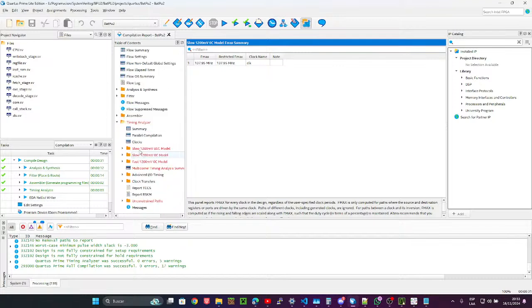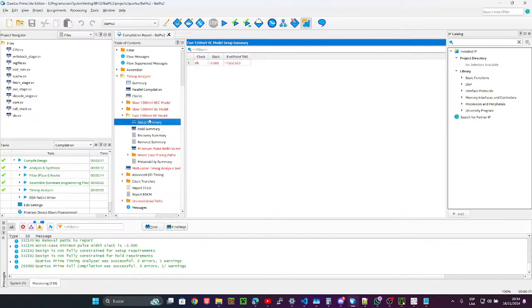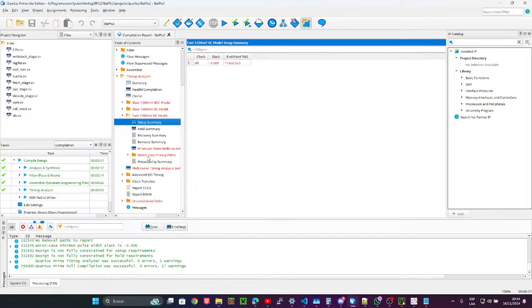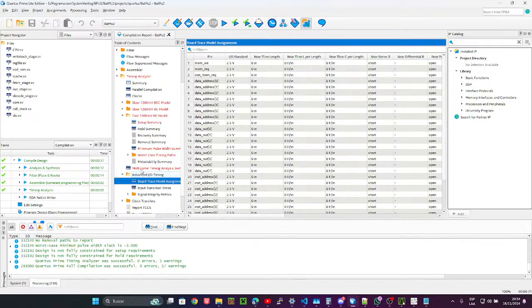To essentially say, give Quartus, in this case give the EDA, some constraints as to how data is expected timing-wise on the outputs, essentially, and the inputs. You can tell it. It's complaining here with red everywhere because you haven't given it constraints.